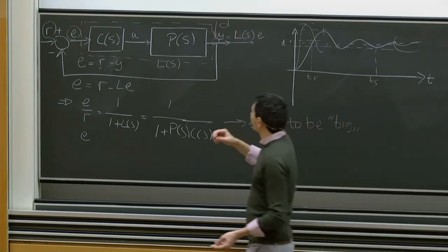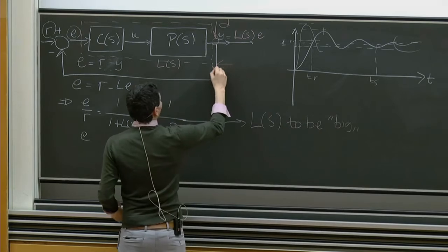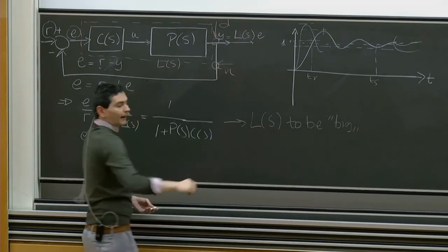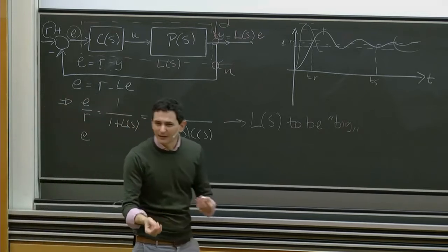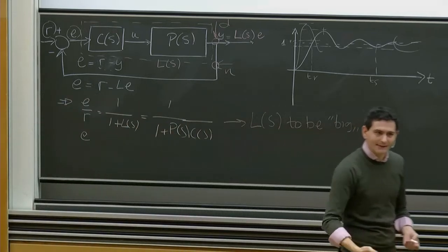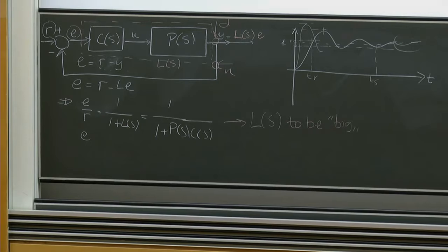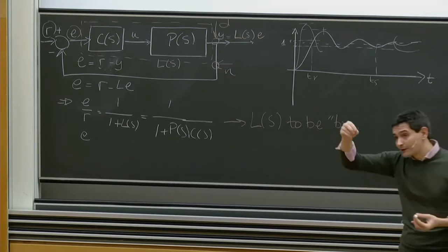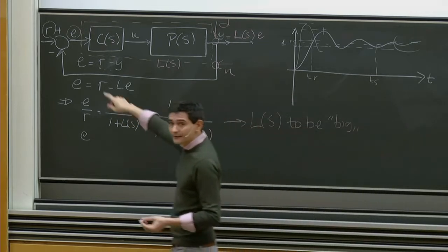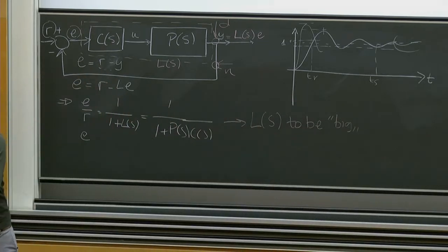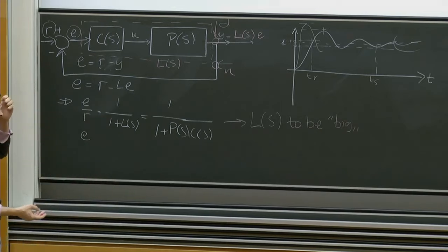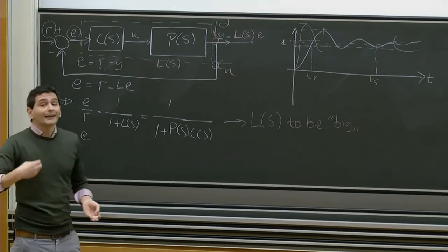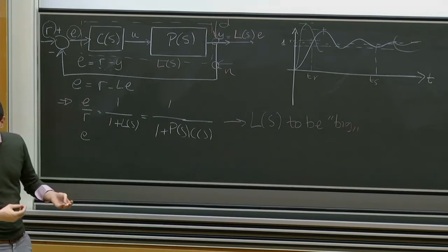And then we saw on the other side, if we had noise coming in, well, this noise is something always unintended, something that typically comes from a measurement device that is being used. It's definitely undesirable. We would like the noise to have very little effect on our output, because the output is what we feed back in the system. So injecting noise in the output means having noise in the closed loop system, which is going to mess up things. We would like to attenuate the effect of noise on the output.